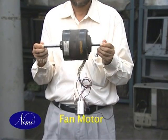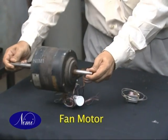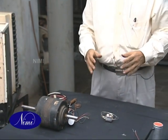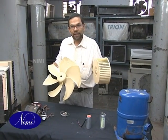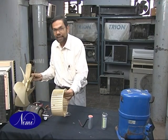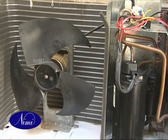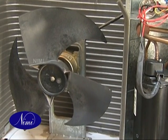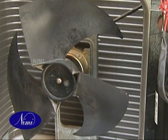The fan motor. What does this do? Like the name goes, it handles 2 fans, the condenser fan and the evaporator fan or the blower. They are fixed on either side of the motor. So this fan motor causes both the blowers or fans to operate and move the air over the condenser coil on one side and the evaporator coil on the other side.